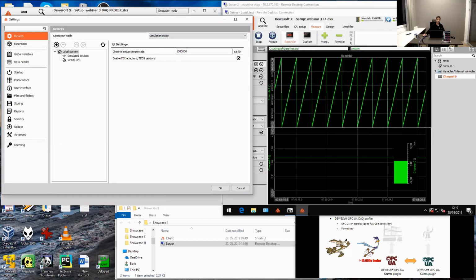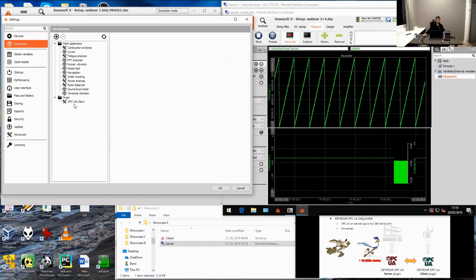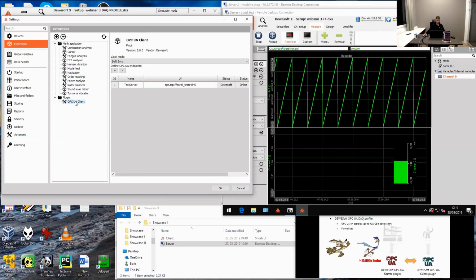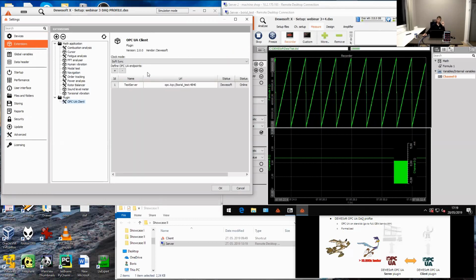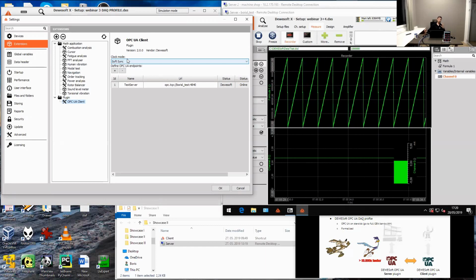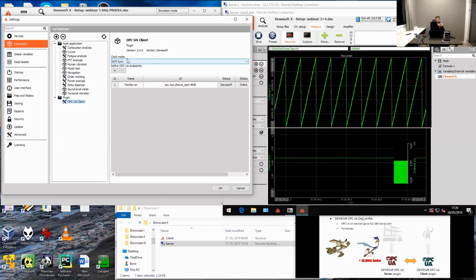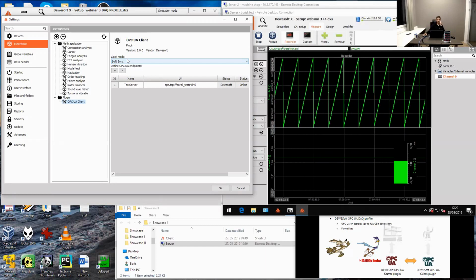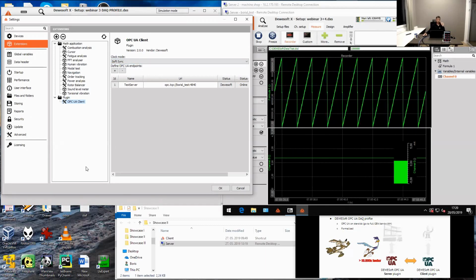And another thing that is important, with high-speed synchronous channels, we prefer master clock, because in soft sync the data gets converted from synchronous to asynchronous data. So we don't want that.